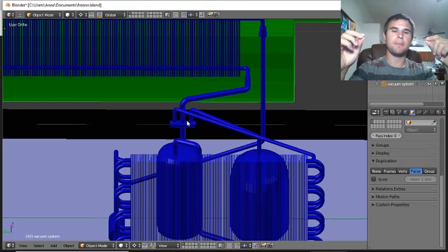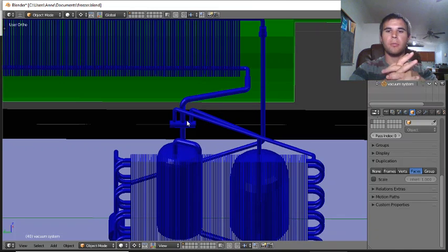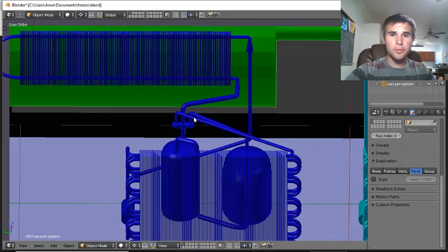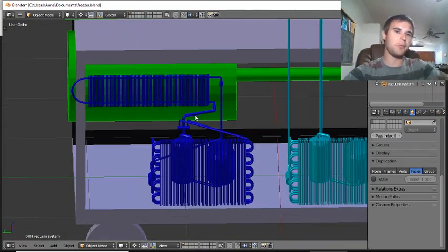I think it would be very hard with a heat pump to finely control the heat levels that we wanted. The heat pump is going to generate way too much heat, so we'd be turning it on and off constantly, and probably just running it too much as a heat pump. And the refrigeration systems that we're going to be robbing out of these refrigerators, you can convert them into heat pumps, but they're not designed for that, and using them heavily as a heat pump you'll end up destroying them, or at least you won't get the results that we probably want. But this refrigeration, the cold trap's refrigerator, we're only going to run it as a heat pump just to melt the ice, so that we don't have to wait for ice to melt.